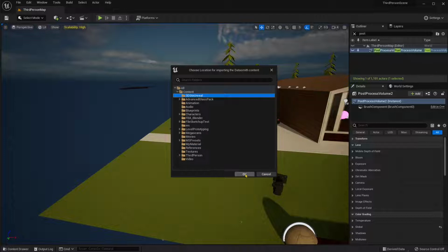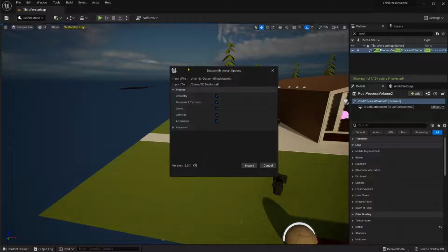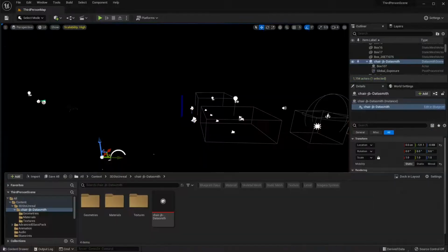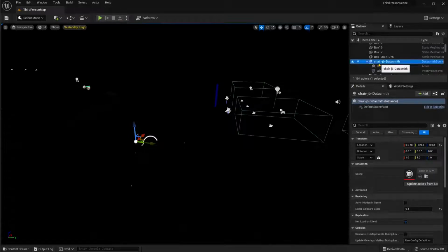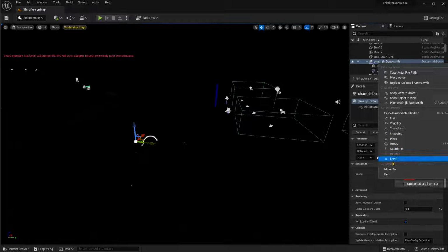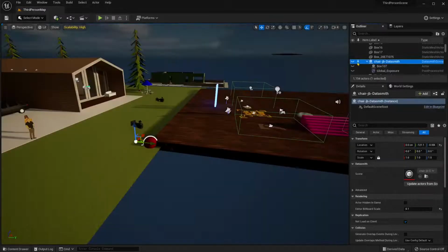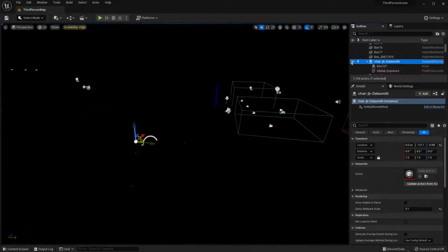Okay, and I'm gonna store geometry, materials, whatever comes from the Datasmith here. So I'm gonna import, and this will be really fast because it's a single object, but you can find it there in the outliner. But everything turns black because it's using something here, apparently. You can see there, I can edit that group. If I turn that off, it's gonna look fine.